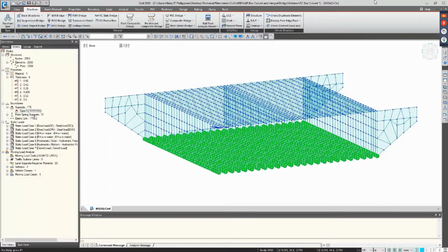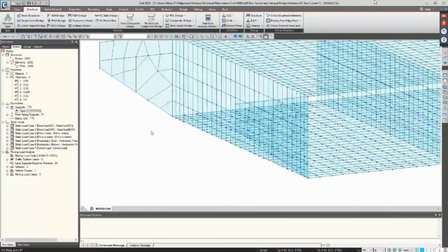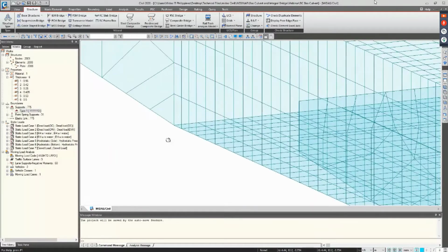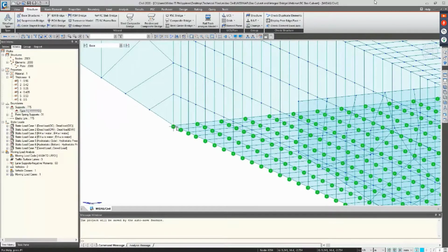So it consists of 6 triangles. Each one represents a degree of freedom. So if all of those triangles are colored green, it means that all of its displacements and all of its rotations are fixed.